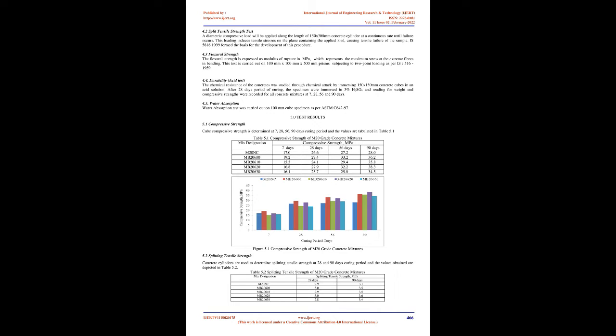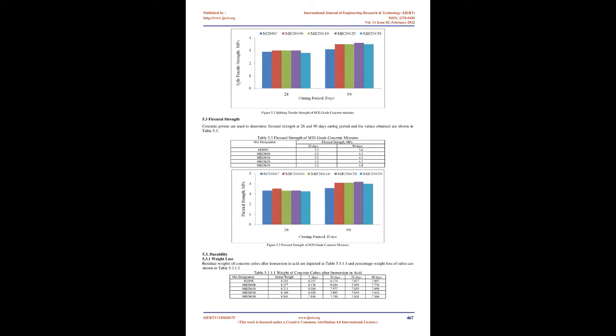Once the concrete hardens, the water supply is cut off, the bacteria become inactive and remain dormant till there is any further supply of water. Hence, it increases the strength of concrete and also repairs the cracks formed, protecting the structural integrity. Bacterial spores are specialized cells which can endure extreme mechanical and chemical stresses, and spores of this specific genus are known to remain viable for up to 200 years. Spores are dormant but viable. Bacterial spores immobilized in the concrete matrix will become metabolically active when revived by water entering freshly into the concrete.